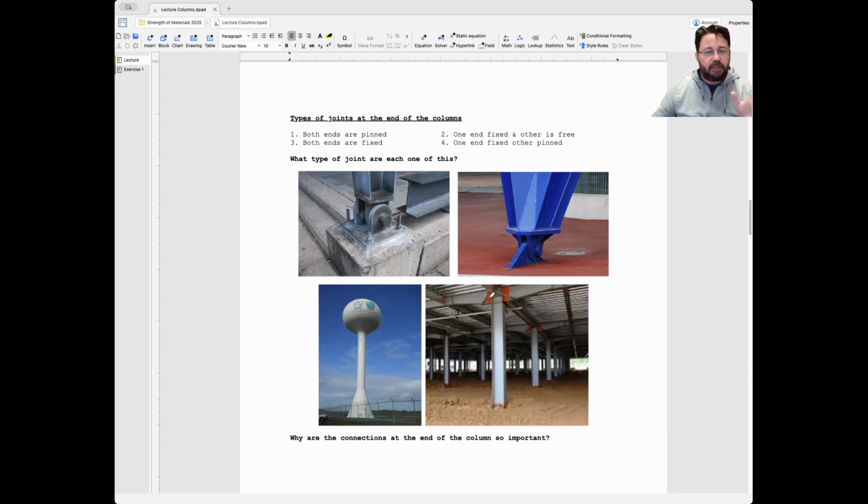Then one important thing about steel structures and concrete structures is that this might seem a fixed end, because if we take it from the planar case, there are 3 reactions. But sometimes bolted connections in steel structures are considered to allow certain rotational movement, so they do not fully restrict any moment there. But that's also case to case. A pin-fixed arrangement could be that you have a pin here, and then this is fixed on the top. Just an example, but that's a very good, insightful question.